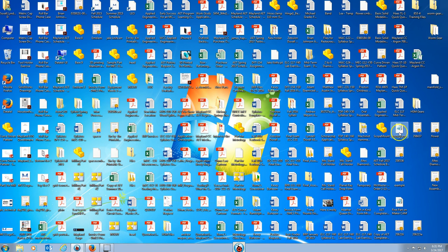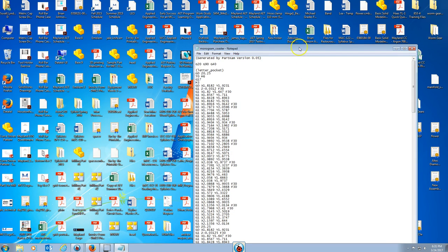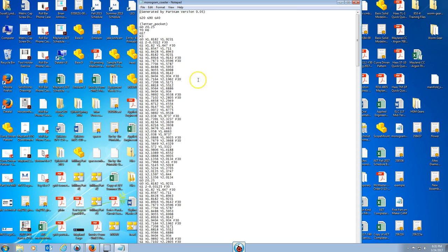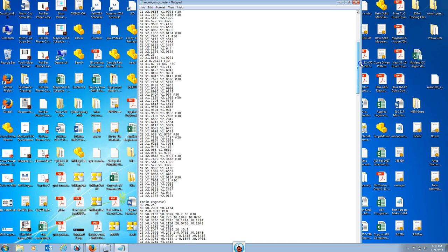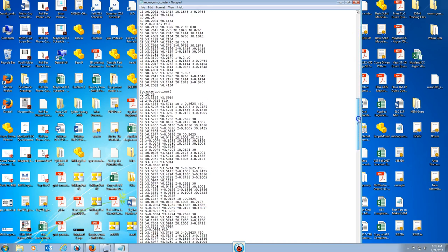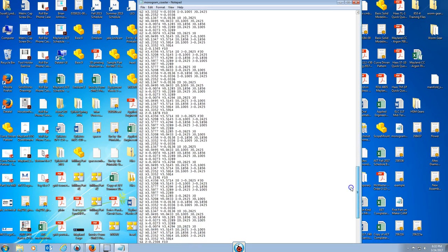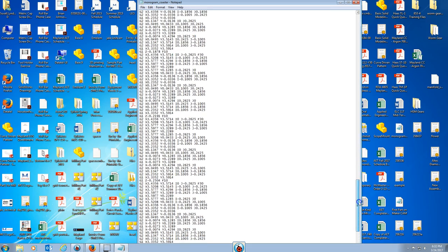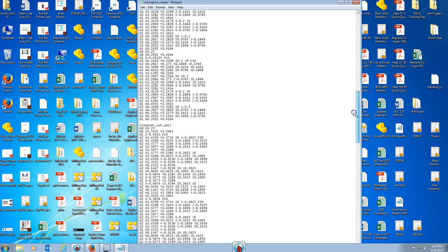It's right here in this area, and so I'm going to double click on that, and you're going to get to see what a G-code file looks like, or an NC file written in G-code. Alright, and so you can see all the instructions that are going to be used to run that machine. And it's kind of interesting, all the students who take CNC classes here start by writing the code by hand, and we start with simple programs and then gradually progress until we get into more complicated ones.